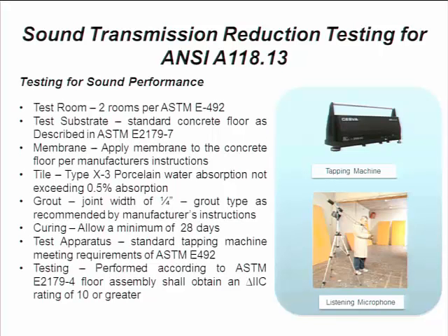The test apparatus, as we talked, is the tapping machine, and it needs to meet the ASTM requirements. And the testing is performed with the ASTM floor assembly to obtain an IIC of 10 or greater. This is the specification that is in the ANSI. It is a beginning specification as I look at it, as 10 is not an overly impressive number, but it was a specification to begin with to say, hey, we need to establish a minimum base and do the delta IIC as a comparative number within that specification.